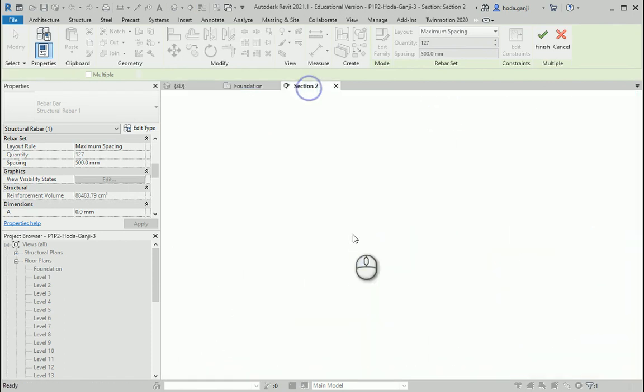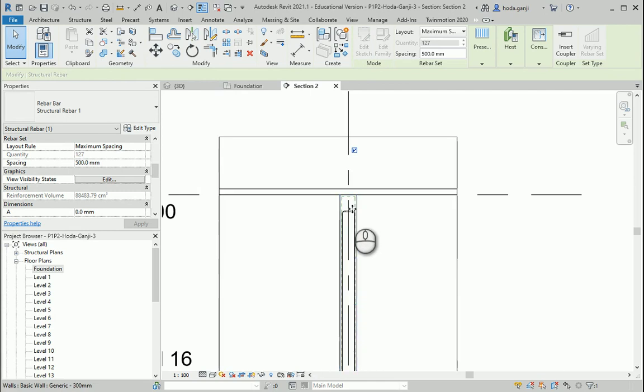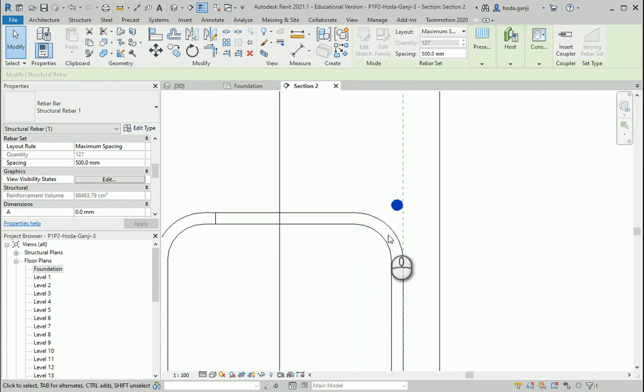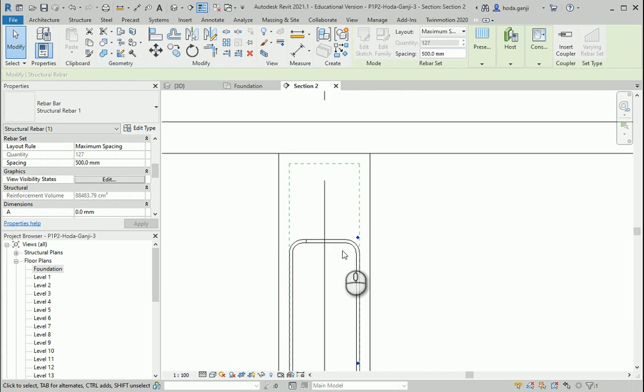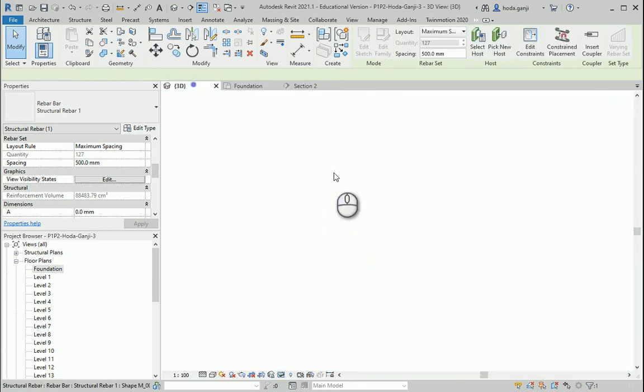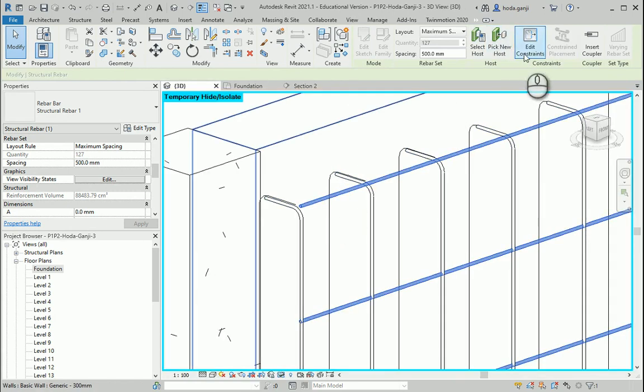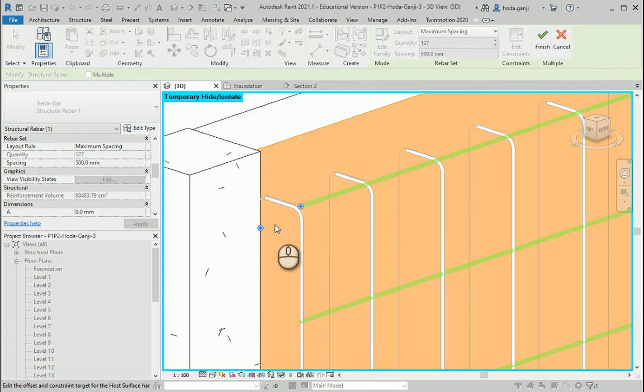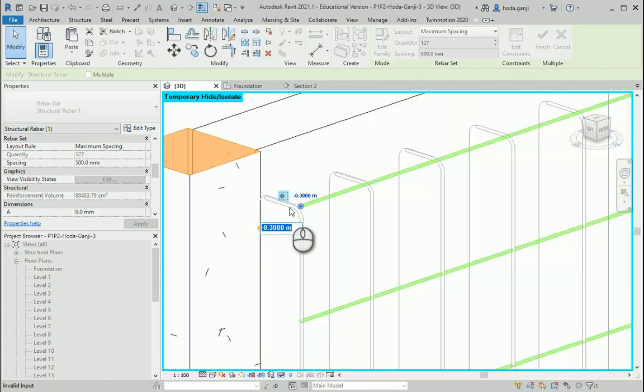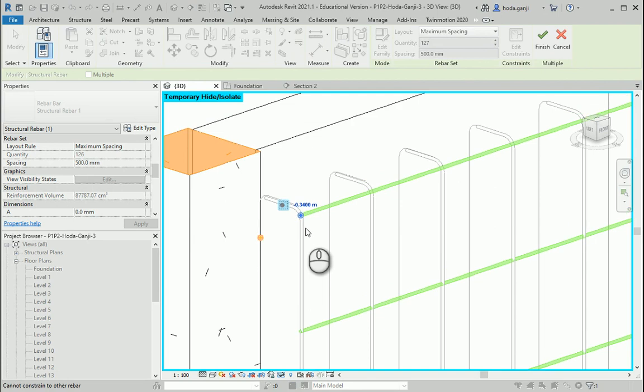Actually, on this side, I can move this a little bit lower and a little bit inside, right? So how about I go back here and go to edit constraint, and to this value I can assign negative 35. That was 34. I meant to assign 35.